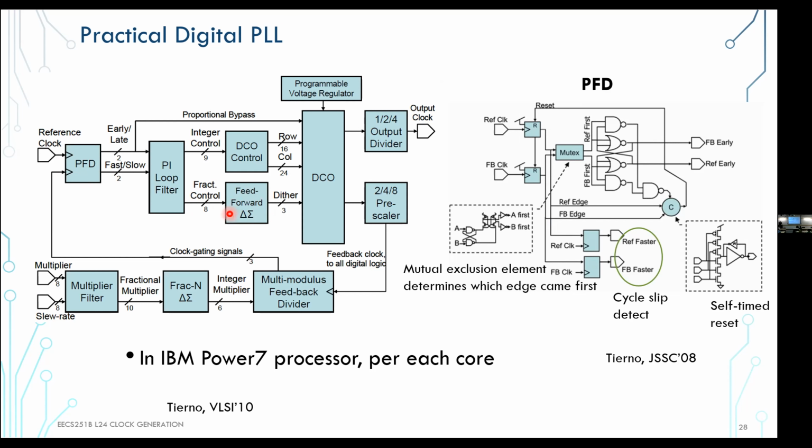So there's a little delta sigma, and of course, delta sigma shapes the quantization noise to be higher frequency, right? And then that goes into the DCO, which integrates the phase noise, right? So it basically rejects those higher frequencies. Right? So that's kind of a trick.